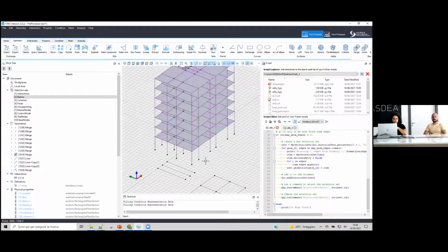This is true for any kind of CAD software. You have to limit the number of times you use Boolean operations because they are very complex, and so the underlying geometry can become imperfect. So if you try to minimize the Boolean operations, it's the best thing to do.